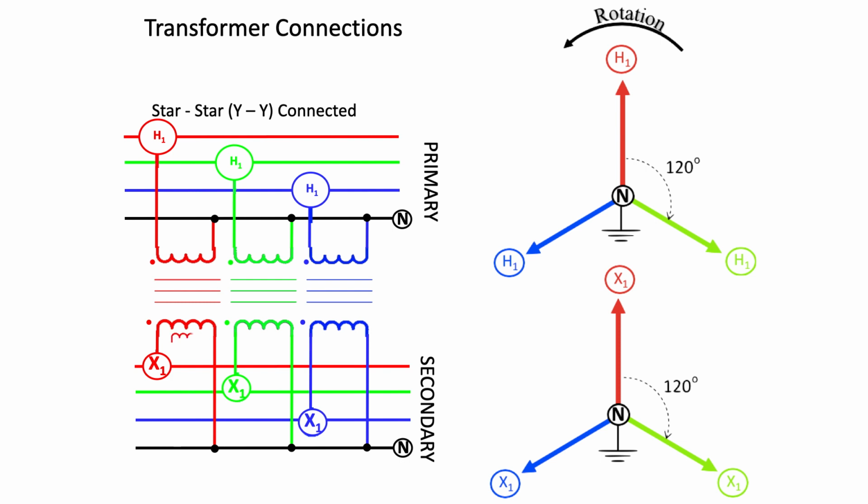This consists of a third winding on each transformer, or each leg of a three-phase transformer. They are connected to form a delta connection. The fundamental voltage vectors look like this, and thus the main transformation may be 230 kV to 110 kV with a circuit of 13.8 kV being fed from the tertiary winding for local use to tie in with synchronous condensers or to supply local power.